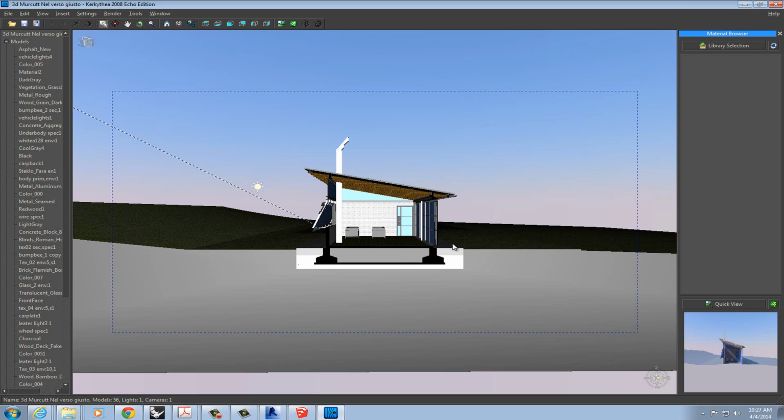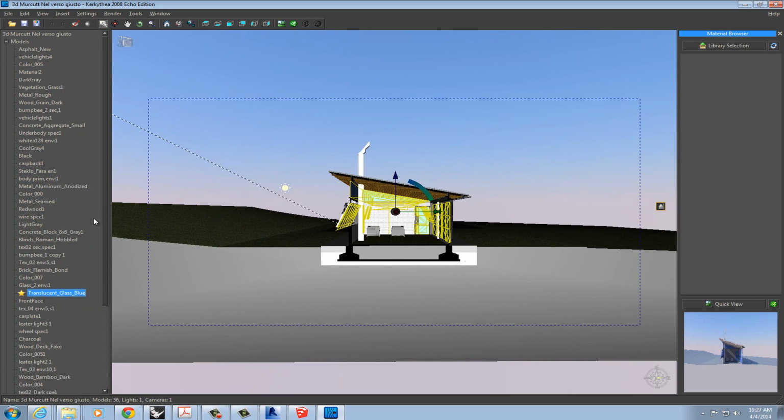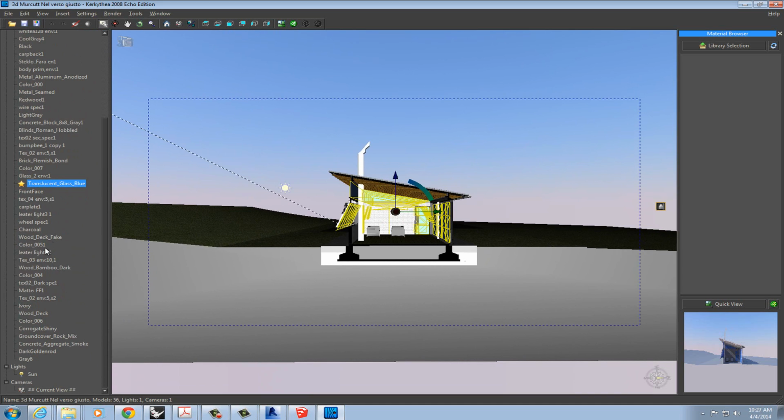And then the second step I usually start doing is applying the easiest material. One of the easiest materials I found is the glazing. You can read through the list of materials in SketchUp. They are the same materials you use on the other side. So if you use a transparent material, it's going to show up here. There are two ways to do it.